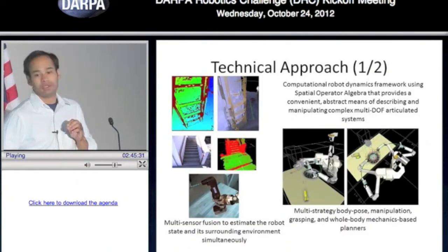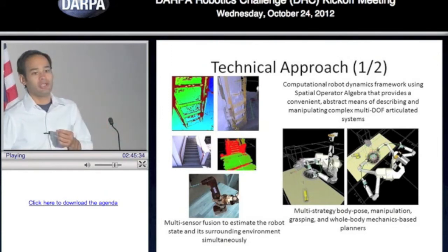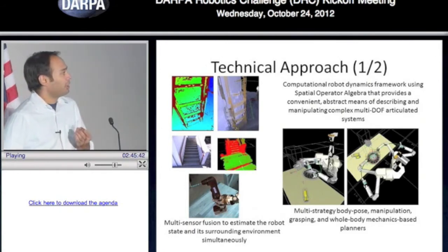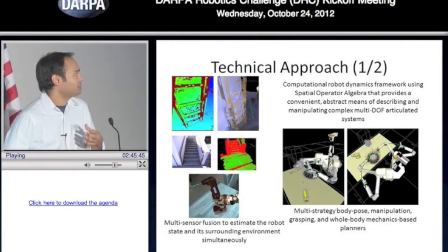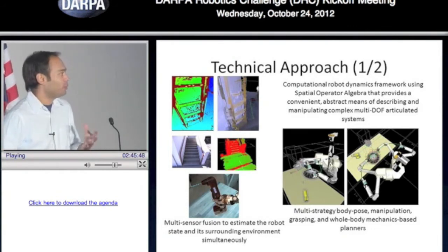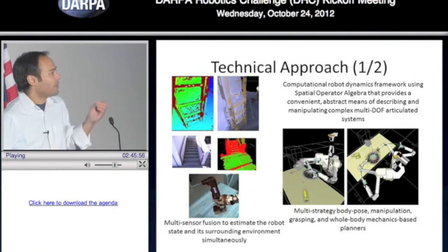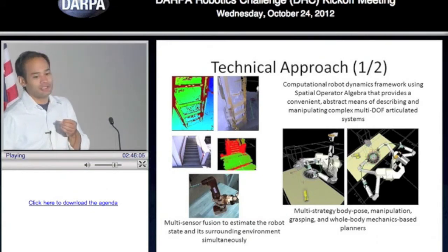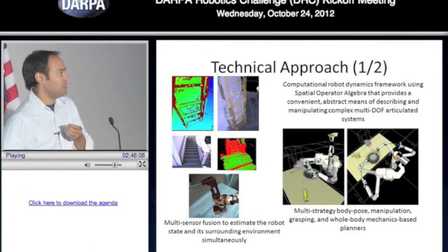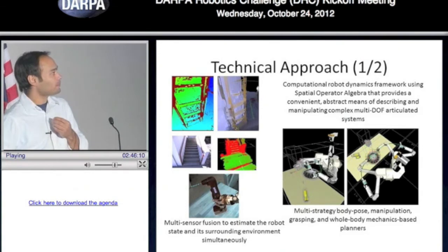Our technical approach is really building on many technologies that we've been developing under both DARPA and NASA and other agencies' funding. As part of the LS3 program, we're delivering near-field perception to enable Boston Dynamics to do near-field perception, obstacle avoidance, and footstep planning. We're also delivering a near-field pose estimation system for the autonomy. As part of the RMS program, we're developing object recognition capabilities that build on 3D voxel maps, and that also allows us to do closed-loop visual servoing and vision-based control, as well as some tactile sensing.